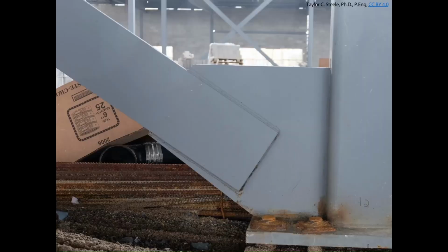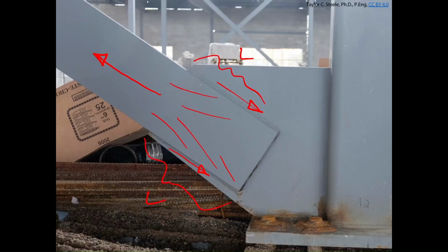I guess what I'll say very briefly about this one is basically when the tension gets applied to the structure or to this member acting as a brace in the building, those stresses transfer down through and into the welds. And so in this case, the welds are going to be sharing half the load that's applied to the brace, or we could consider the total length of weld as being equal to this length plus this length. And so here for us, the total length of weld that we have would be 2 times that L value.